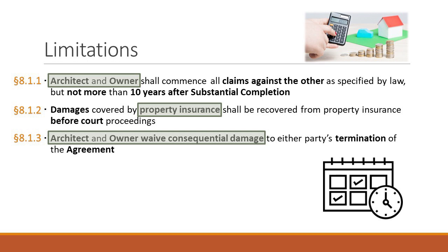It's if you knew or should have known within 4 years to bring a claim, and that's the period where it says the period specified by applicable law. But in any case, not more than 10 years after substantial completion. Now, if you remember in Illinois, it's that 4 years, but there's the 10-year discovery period, so that's called the statute of repose. So it could go up to 14 years. So this provision would limit it to 10.